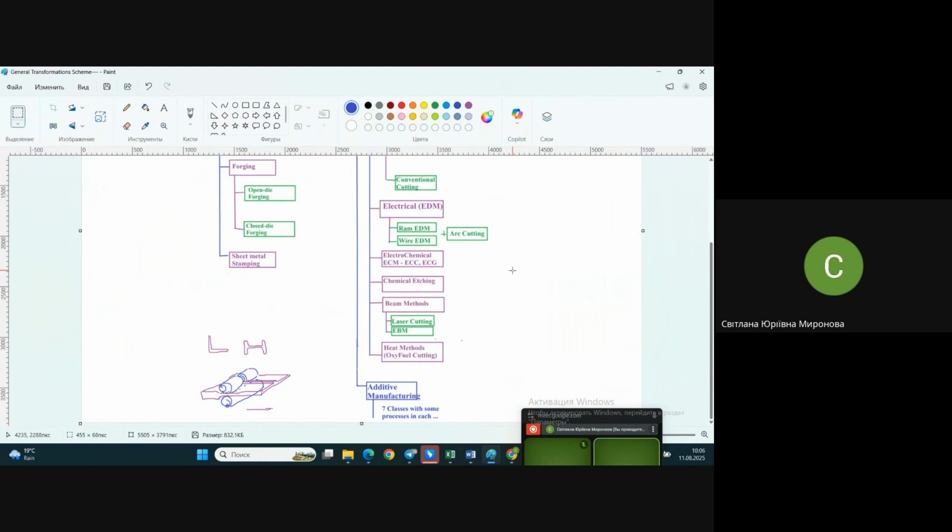It means that there we use a conventional mechanical tool, like a grinding wheel, for instance, or the same disc mill, but with addition of a liquid able to provide electrical contact with higher quality, and cutting will be inside of a special liquid with additional acting of electrical discharge, but by a mechanical tool.